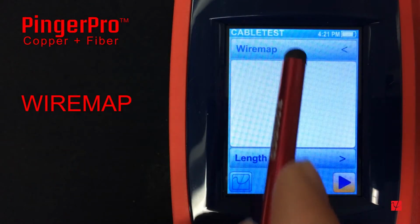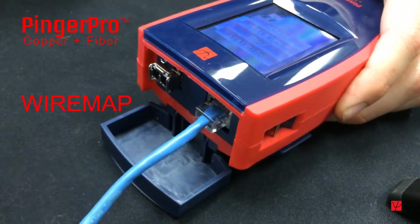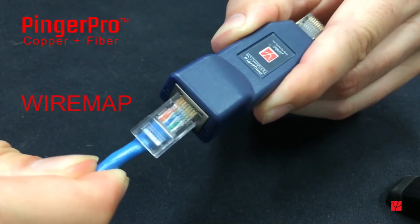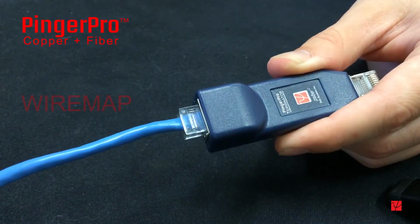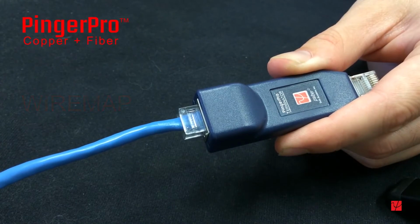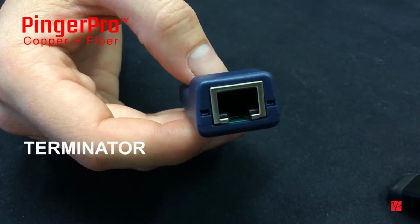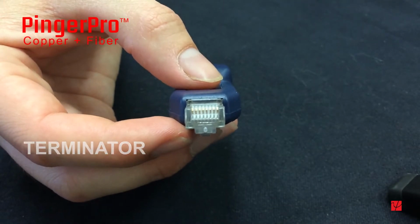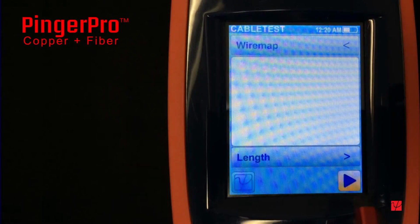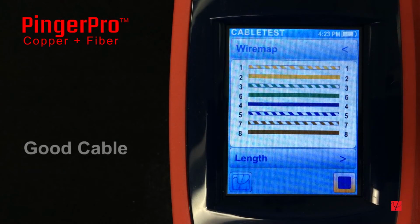Select the WIREMAP test and plug one end of the cable into the PingerPro and the other end into the WIREMAP terminator that comes supplied with the PingerPro. The WIREMAP test will not work unless the WIREMAP terminator is attached to the far end of the cable under test. The PingerPro terminator is designed with a female jack for testing cables with an RJ45 connector and a male RJ45 plug for testing cables connected to a wall outlet. Pressing the play button will begin the test. This is the WIREMAP of a good cable.